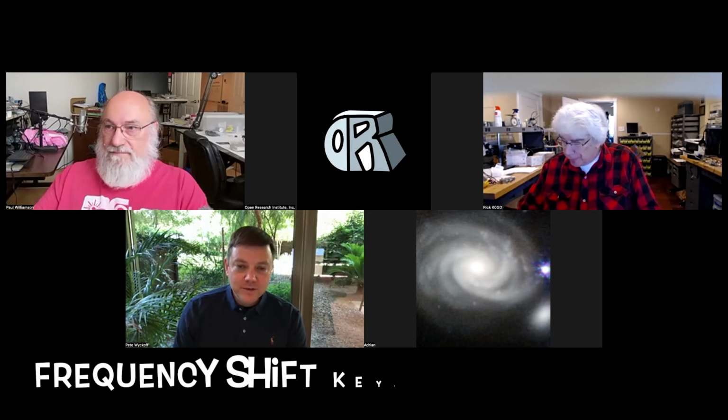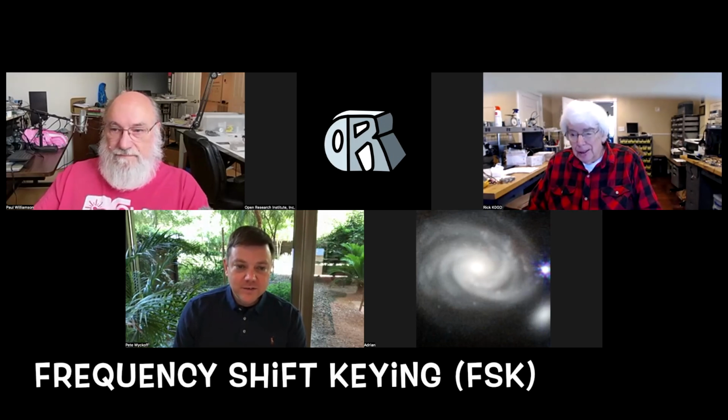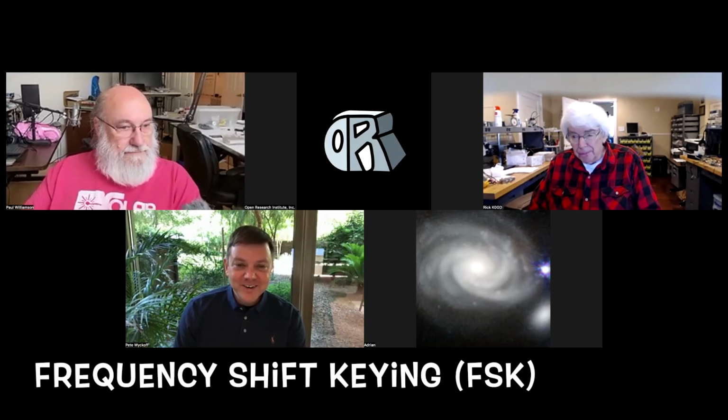So the good news is part two will have a lot more pictures and a lot less math because I found some better ways to explain things. So I think that'll make part one clear as well as part two. So sort of a summary is there's three waveforms I'm working on right now. One is an FSK waveform customized for Eve. And that's just looking at what's the best FSK waveform and demod we can make given the link budgets of Eve. That's pretty straightforward. Low risk since we have experimental data from sending tones back at inferior conjunction a couple months ago.